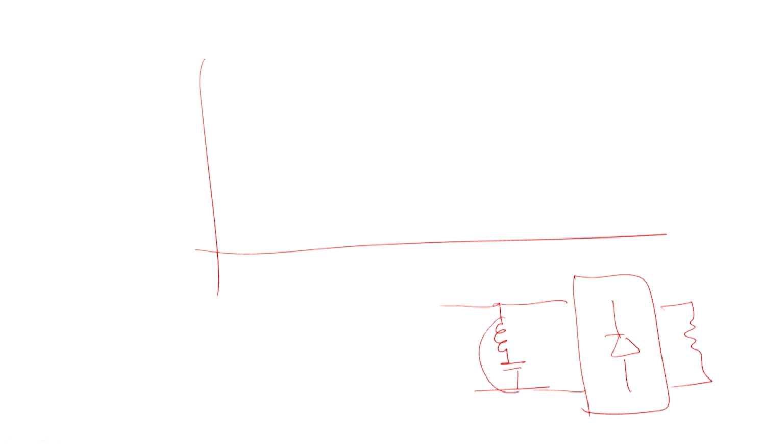You are connecting a passive filter here, thereafter I am drawing the single line diagram. Thereafter you may have a diode bridge rectifier for single phase, let us say. Now, this has to be tuned if it is compensating for the third harmonic. So, the response should be like this. You can design the filter some way; third harmonic is 150 hertz. So, it has a component of the 150.